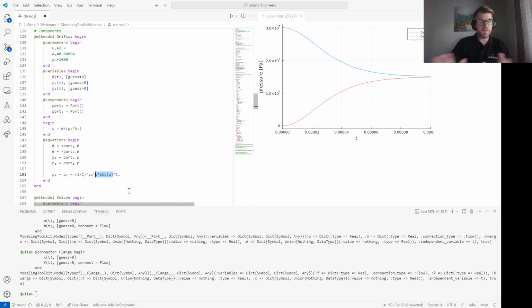And that's all fine. However, this still has one more issue, which is that a square or a square root of something gives a zero differential. So when we're squaring something at zero, the derivative is zero. And for a solver that is using gradient descent, such as Newton iterations, that becomes very problematic because there is no longer any descent if your derivative is zero. So there is a fix to that problem,